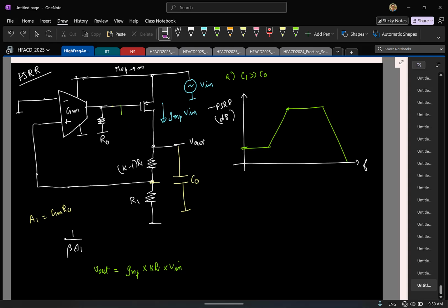Okay. See, the idea is, I cannot prevent the fact that the capacitor will act like a short circuit at high frequencies. That is something we can't change. Now, it is us who have put this capacitor from this node to ground. Which means if the capacitor acts like a short circuit, this node is shorted to ground. Now, what I am saying is, when the capacitor acts like a short circuit, I want the change in Vin to be coupled here, right? So instead of putting the capacitor to ground, I can connect it here. Because remember, technically this is a supply VDD, that is also small signal ground typically. That makes sense?